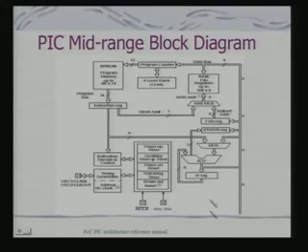Most probably your software has forced the microcontroller to go into some infinite loop or error condition, so that the system is not in a position to reset the counter value. This is a generic concept of watchdog timer in an embedded system. So when the timer finishes its count and it has not been reset, it will generate an interrupt, and that interrupt will enable the system to go back to one of the known predefined states. Okay. So this watchdog timer is a very important component.